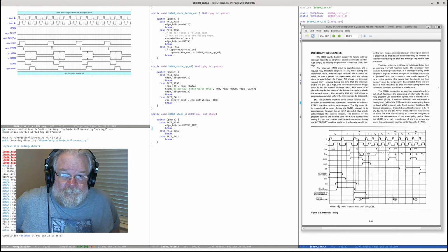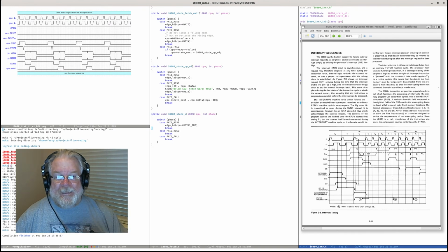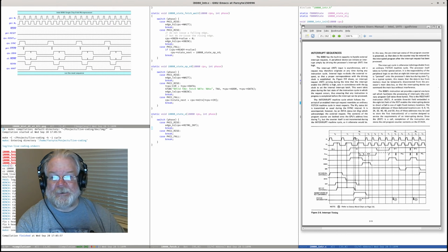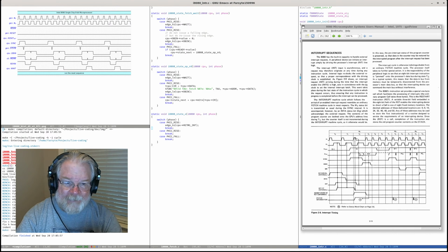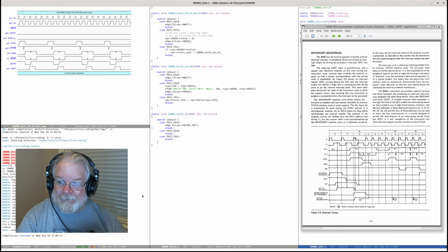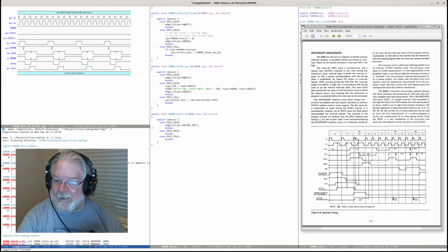The other thing is when you do an enable interrupt, we want to make sure when we write the logic that if we got an EI followed by an instruction, we can't get an interrupt before that instruction is completed. And the pipelining should work on that. As I said, I've prototyped a lot of this before, and I remember that the pipeline fell into place. So we have here some problems.